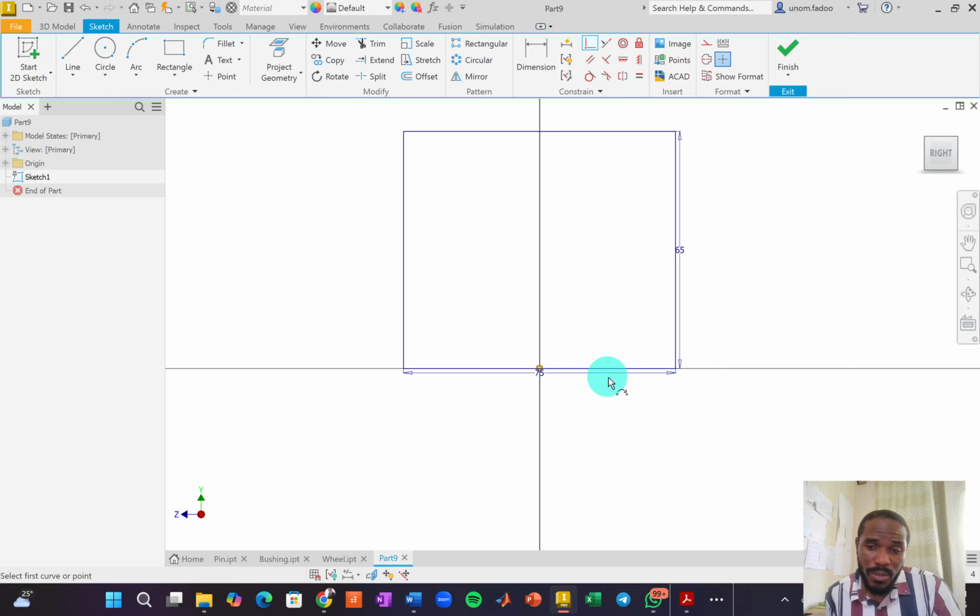Now, I could at this point provide the fillet, but I'd rather do that in the 3D space. So I'm happy with this. Next thing is the circle. I'm going to pick a circle, click here and drag out. The diameter of that circle was 12. Enter. Okay, there's another one this way. Diameter is 12. Enter. Okay, pick my dimension to the distance from the back end or the upper end of this guy to the center of this was given to us as 35.